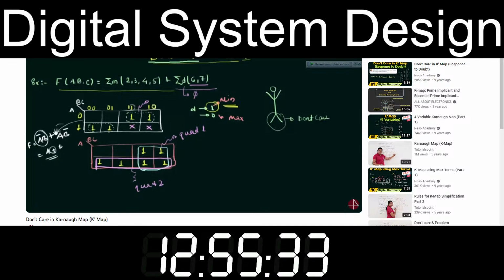So you can see this, and now I'm going to write the function from this k-map. So this is 0 1 0 0 0 1 1 1 1 0. Let's write it for the quad 1. In this quad 1, A is changing from 0 to 1, but B is not changing, it is 1, and C is changing from 1 to 0. So we have just A reduced and also C eliminated. We are left with B.